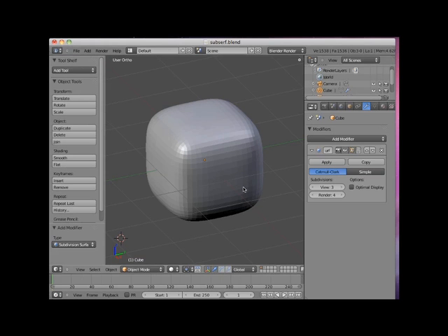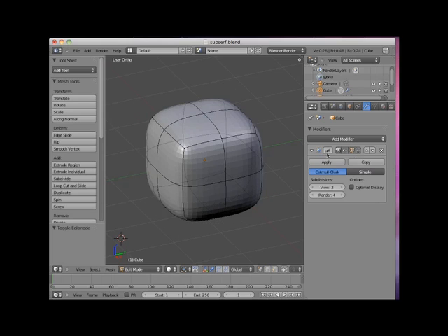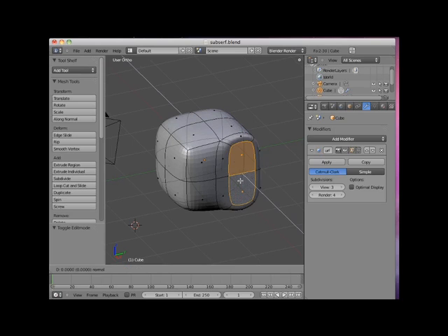It is quite common for modelers to model an object while in edit mode with the Subsurf modifier applied to the object. To facilitate this type of modeling, the Subsurf modifier has an Apply Modifier to Editing Cage in Edit Mode button. Activating this button collapses the object's mesh around the subdivided surfaces, which makes it easier to visualize the modeling effect. I will go to Face Select mode and select some of the faces, and extrude them and move them around a bit.